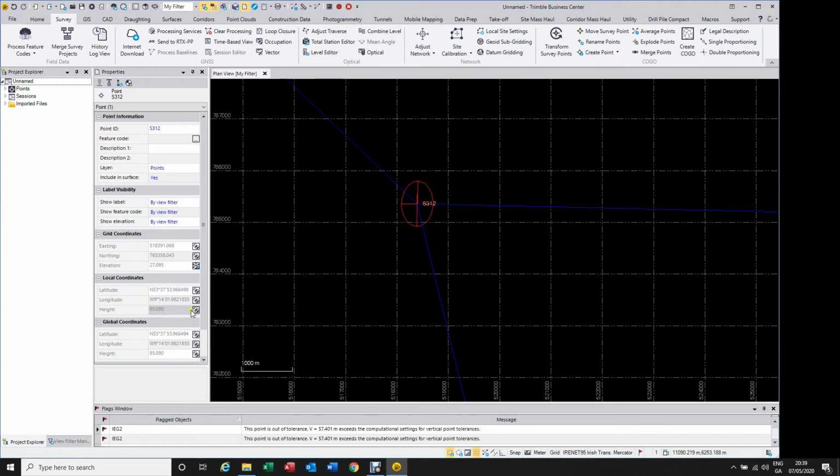That's what I was going to say earlier. The ITM is using the GRS80 ellipsoid, which is very similar to the WGS84. I think the long axis is 100% the same, just the other, smaller axis is a bit smaller, I think.